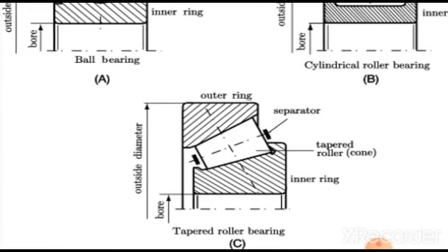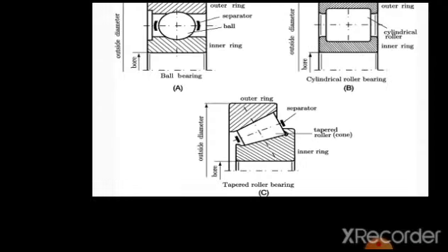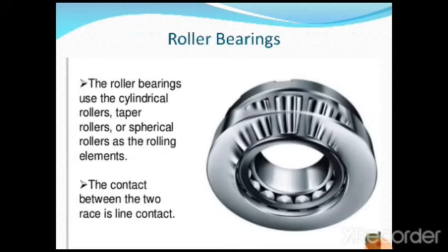Similarly, tapered roller bearings are also used. Whatever type of bearings there are, those are used depending upon your type of machine, the capacity of the load to be carried by it, and at what speed requirements of the spindles there are. So that decides the type of bearing that can be used in case of CNC machines.